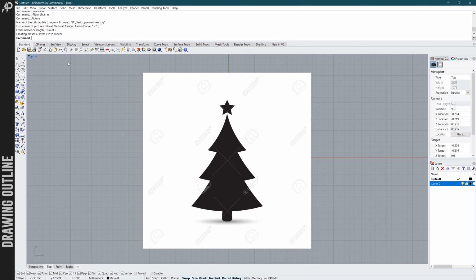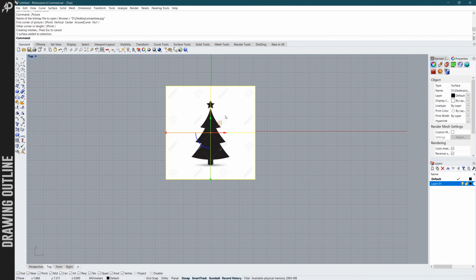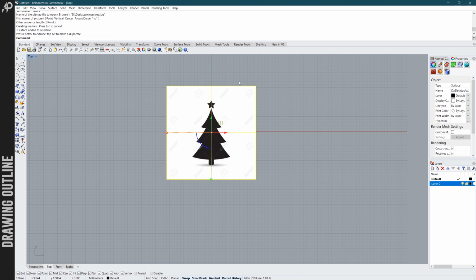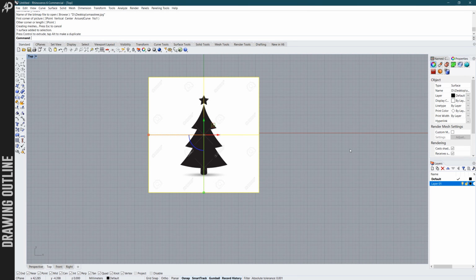And this is it. Now we can move our object freely, but since it's our base object, we don't want that, and for this purpose we will use layers, as I've mentioned. So I already have one layer created, but if you didn't have it, you can just right click the layers button and click on new layer, give it a name of your liking.